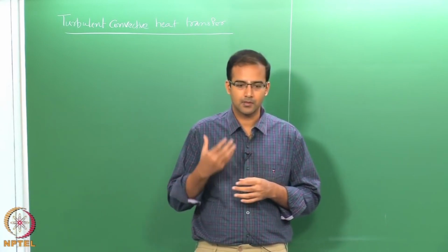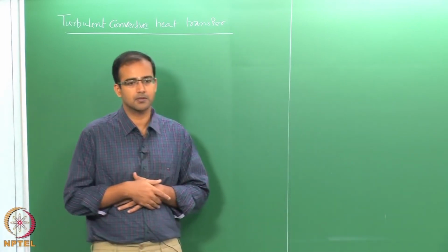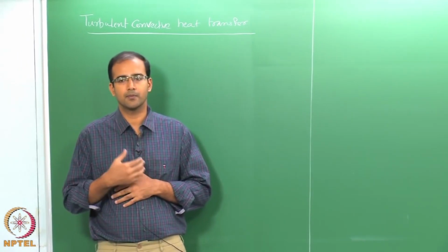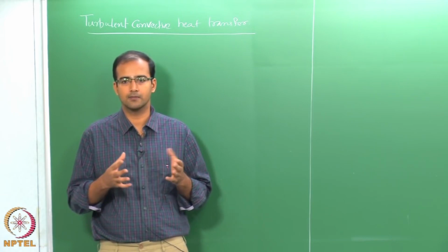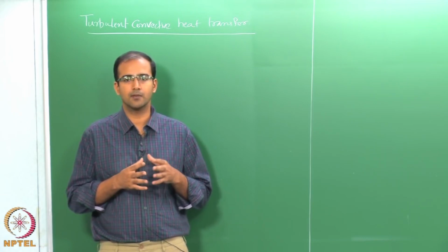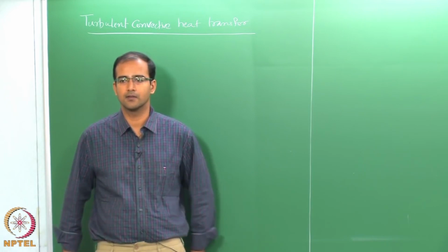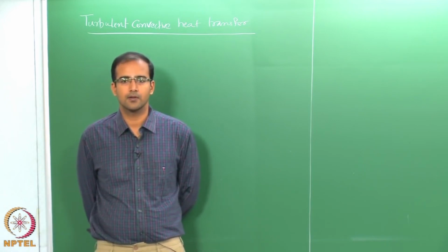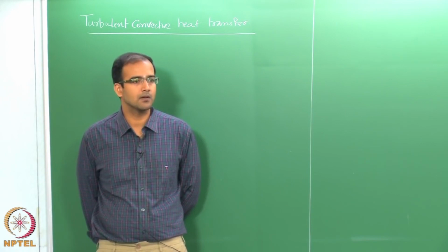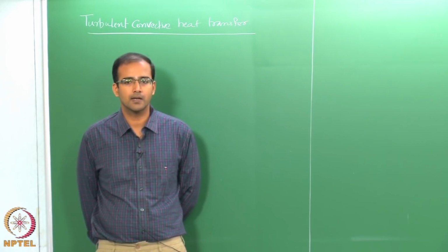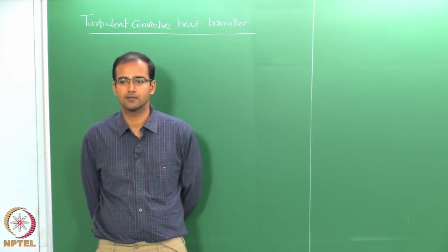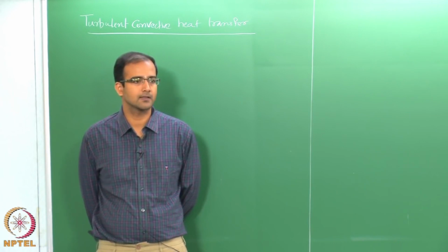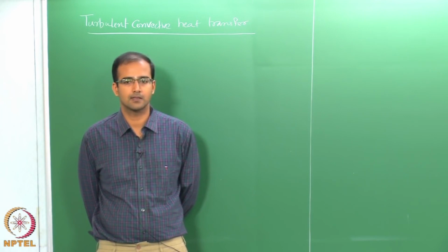So, when it comes to turbulence, again people have different approaches to it. My personal approach is also, I do not look for analytical solutions everywhere, but you should understand that for certain problems there are analytical solutions available which you should not overlook. For example, I have seen cases where people solve the flat plate boundary layer numerically and they do not know where to look for the Blasius solution to validate. So, you should know by now for which cases you can actually compare with exact solutions.